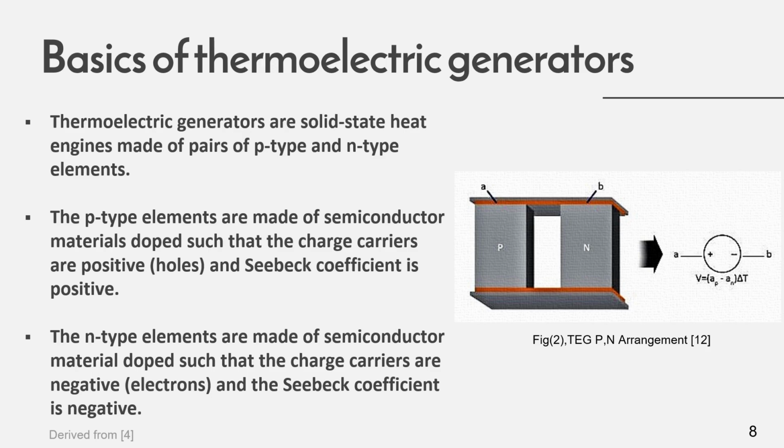And we have discussed the materials used for building thermoelectric generators, and from the observations made, it is found that mostly semiconductor materials hold this property to a great extent. So rather than using two dissimilar conductive metals, what we normally use in practice is to select a semiconductor material and dope it with p-type and n-type elements to make two dissimilar materials.